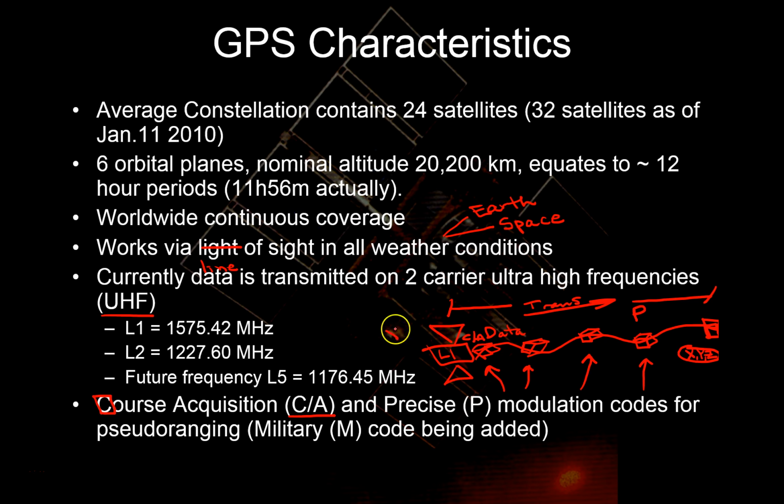Ultimately we also need the coordinates of the satellite. So it gets closer to traditional surveying, where we consider the satellite to be a control point with known coordinates. We then have a distance measurement to that control point, and we can use several of these measurements to several satellites to figure out where we are. We'll talk about this coming up, called the fundamental positioning problem.